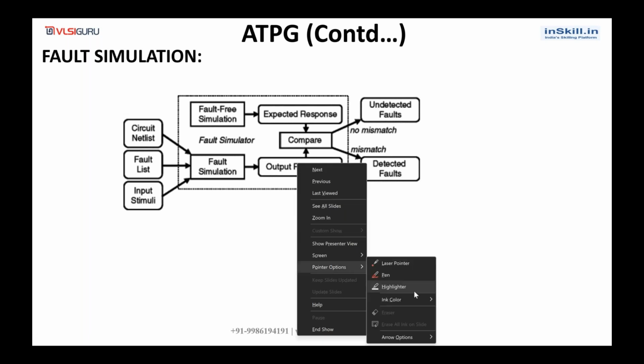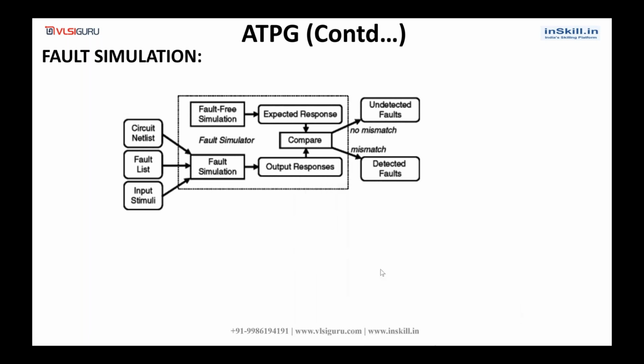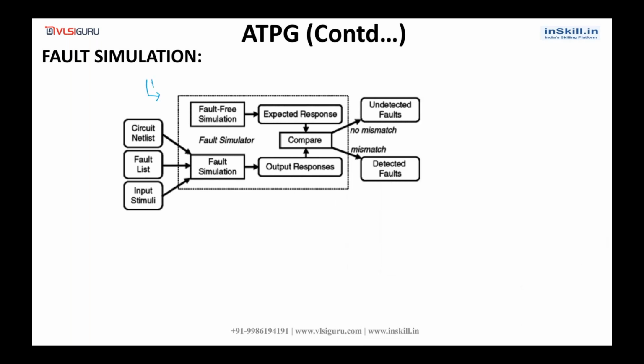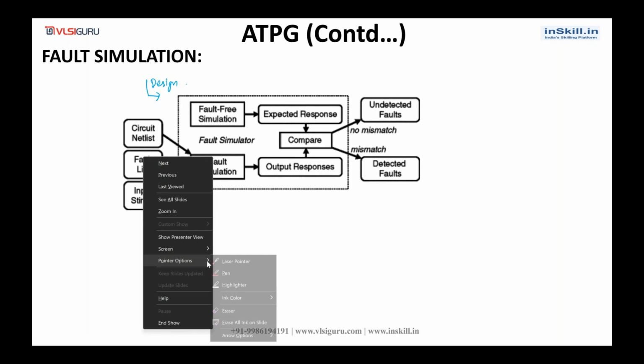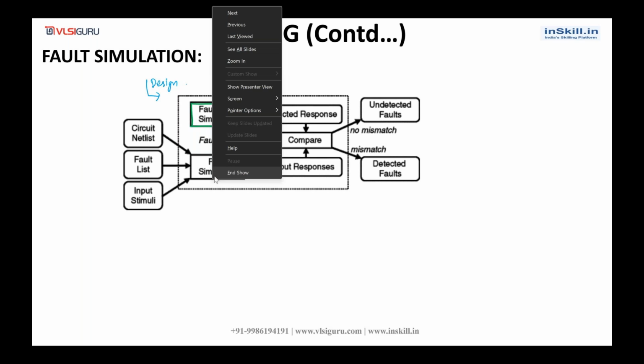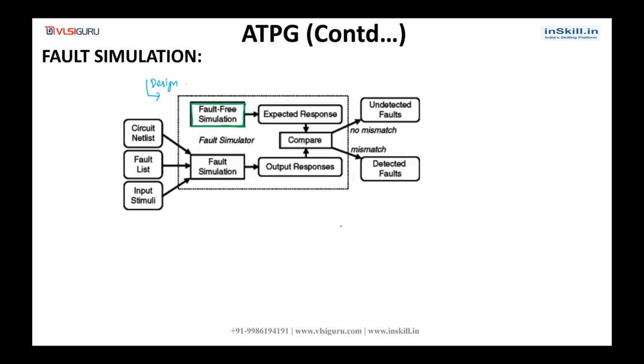At the time of ATPG, we will be giving our design to the tool. The ATPG tool will keep this design, and everything will happen in its internal memory itself. In its internal memory, it will create another copy of this design.